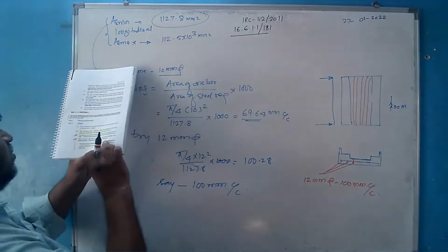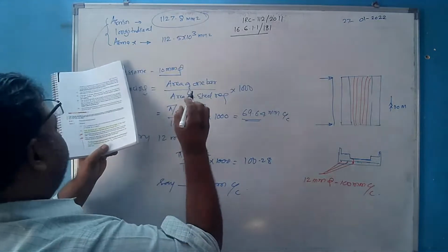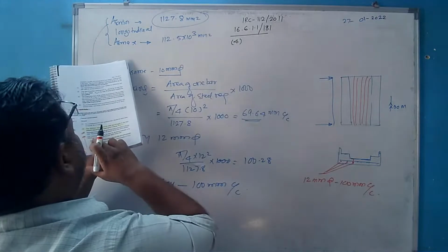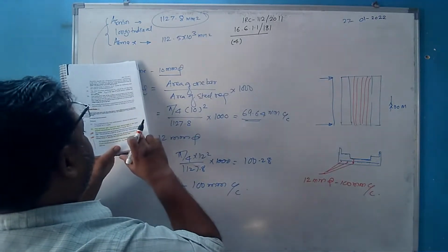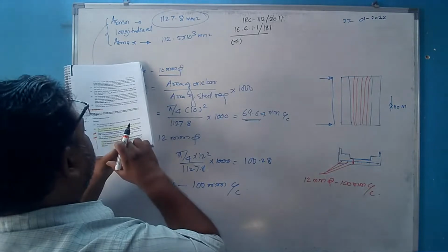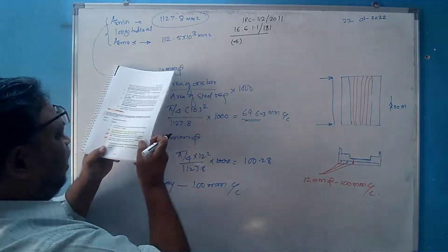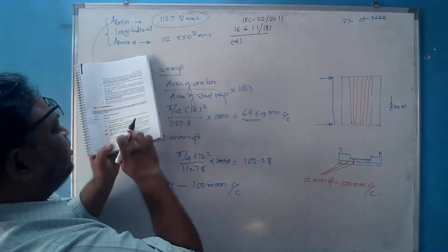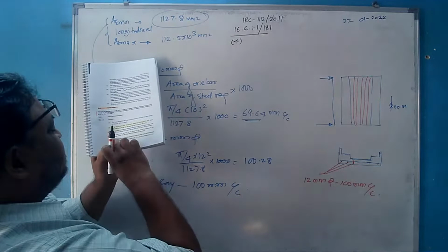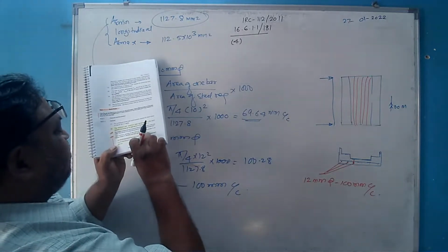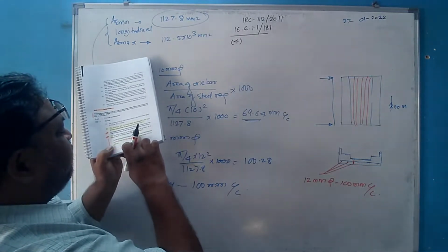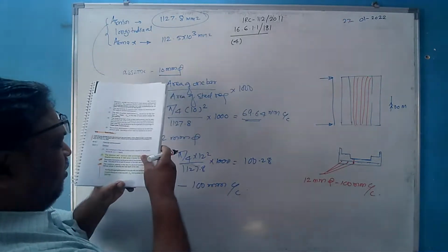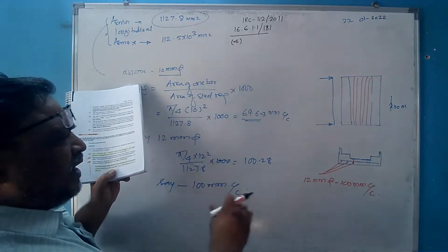Here you will find the fourth part of that clause. What is that? The maximum spacing of the bar for structural purposes is as follows, where H denotes the total depth of the slab, for the principal reinforcement in one-way slab and reinforcement in both directions in two-way slab. Principal reinforcement in one-way slab, that is nothing but the reinforcement in the direction of the span.